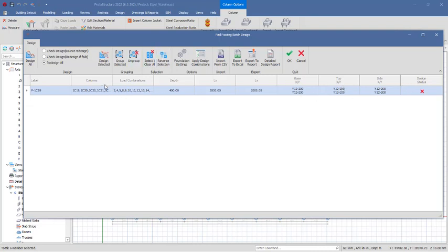After we have done this, what we now do is come to Design All. You click these options, Design All. This is going to design and assign the same footing size to both LX and LY of the footings successfully. You just have to give the program some seconds to carry out this design. So now the design is done.